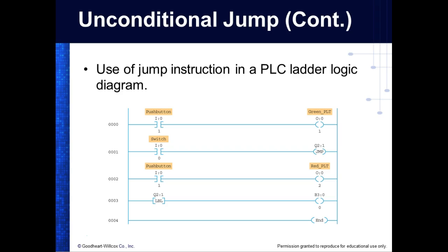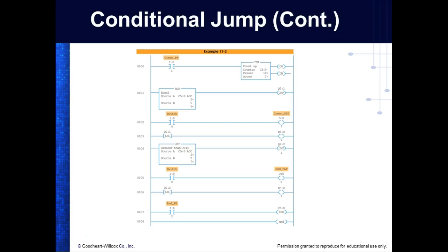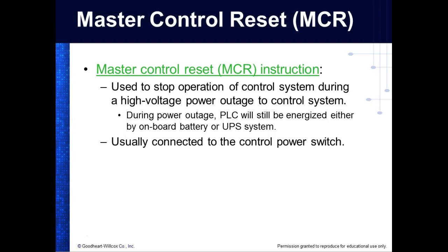Allen Bradley supports two types of interrupts. One they call a timed interrupt. What do you think that means? Yeah, we use the timer, the timing register, and we have it come back and check that after a time, right? Does that make sense? So now we're not dependent on the scan time. So I might want to update something every minute. Well, instead of me trying to do that with a timer, I could set up a timed interrupt that occurs every minute. And then every minute it would go out and run that subroutine.